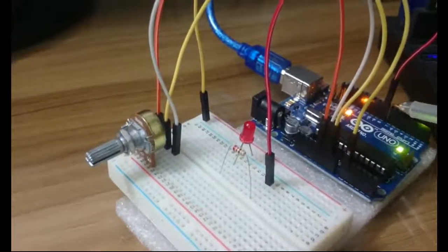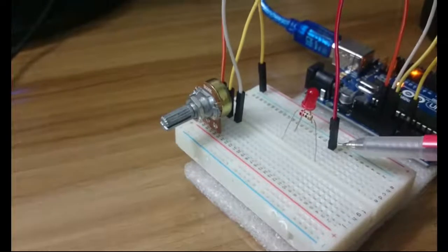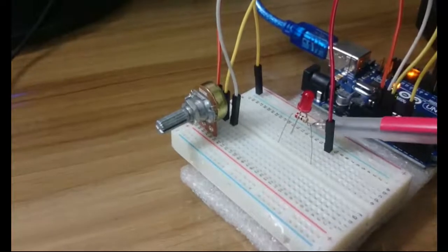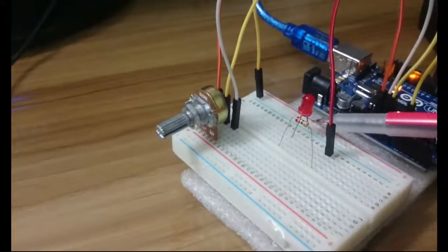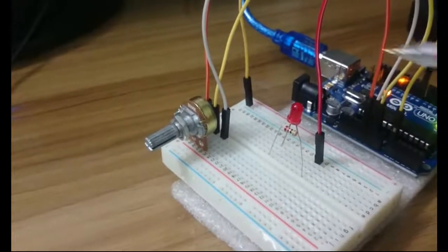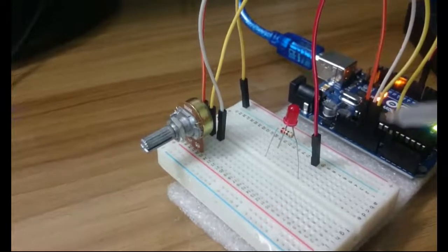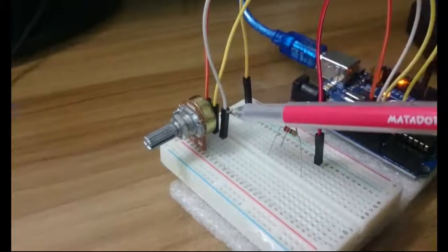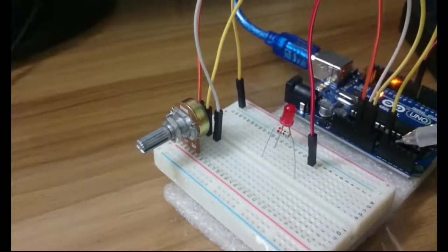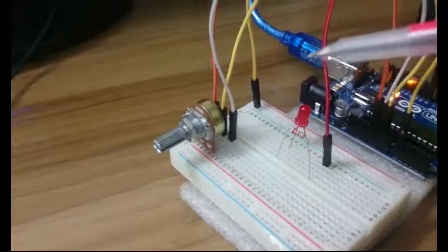I took the digital 8 output pin from the Arduino board, and I put this digital output pin to one part of the resistor, and the other part of the resistor I connected to the anode of the LED, and I put the cathode of the LED, that means the negative terminal, to the negative rail in the breadboard, and I connected the negative rail to the ground of the Arduino board, and I connected another ground of the Arduino board to one terminal of the potentiometer, and I took the analog A0 connection from the Arduino board and put it into the middle connection of the potentiometer here.